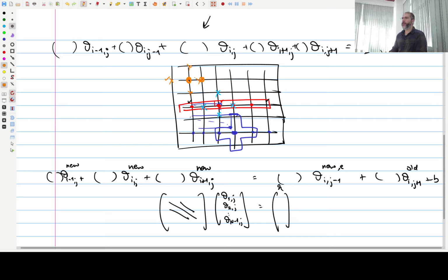And that is the reason if you have a higher order scheme: a lower order scheme will have fewer points, and a higher order scheme will have more points. So more points talk to each other. If I had a third order scheme in this case, then I'll have one more point in the x direction, one more in the y direction. That means more talking is happening, so things will happen much faster, but then you have to do more computational work. So this is the reason that it converges much faster.